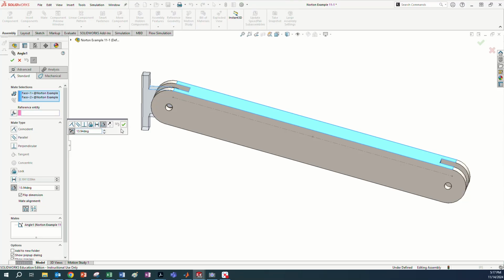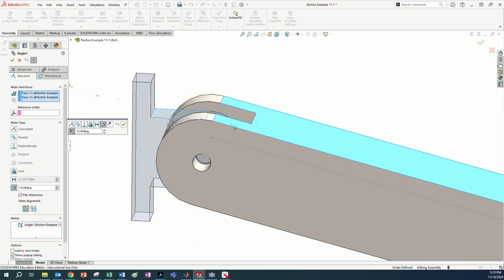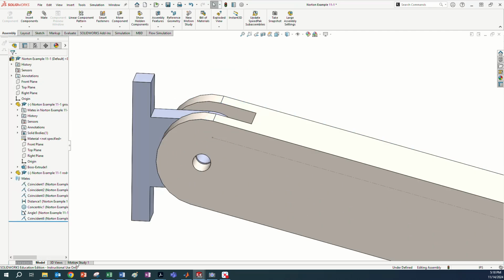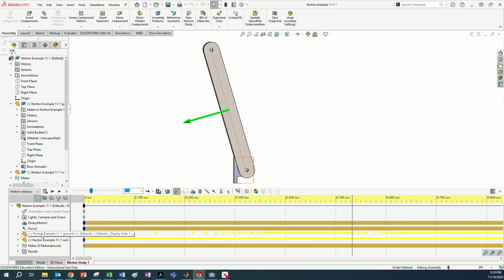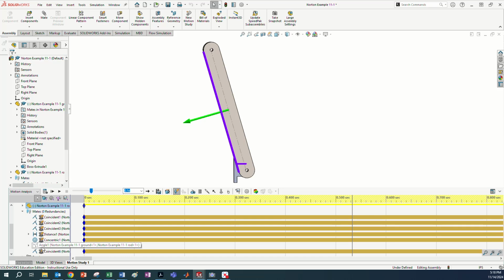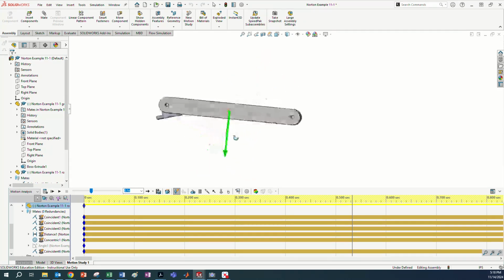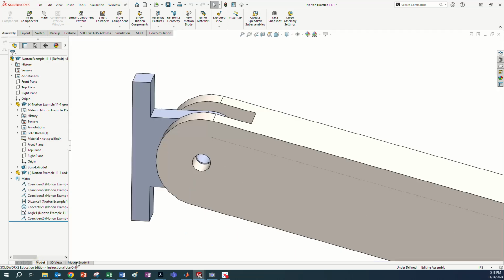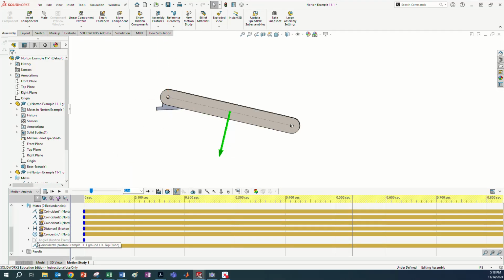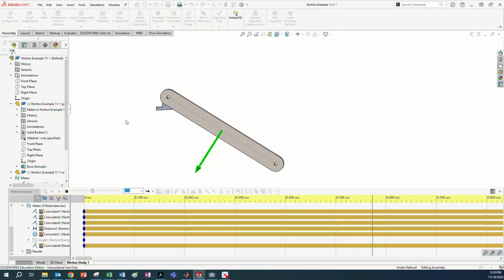So there was the angle, and I made it 13.94 in between here and here, right? And when I created my motion study right at the beginning, I took that and I suppressed that angle. So I started exactly at the right spot, like right there, when I was in the model mode over here. But when I go over to the motion analysis, I suppress it, and it will start in the correct position, right? So we might as well run the thing while it's right there.